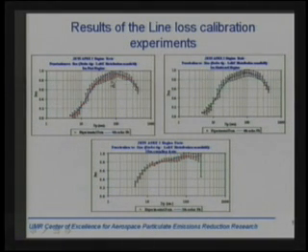What we do with the data is we take our instrument values and then we deconvolve the particle losses that we've demonstrated are taking place, through these plots, to predict what the concentration was as it entered the probe tip. That's going to be in the post-processing. But it's critical to measure these on all of the sampling systems so that you can account for those sampling artifacts.